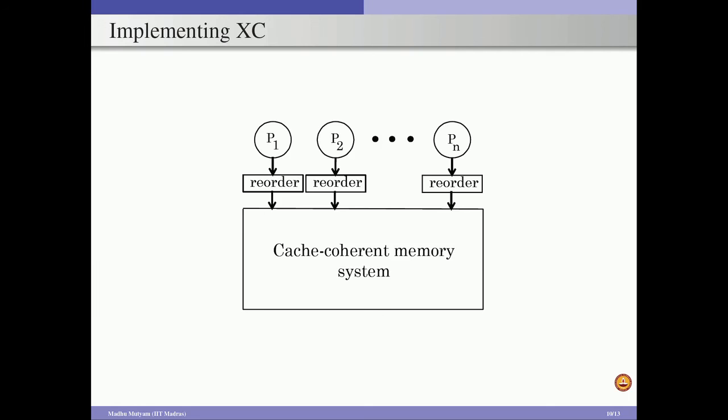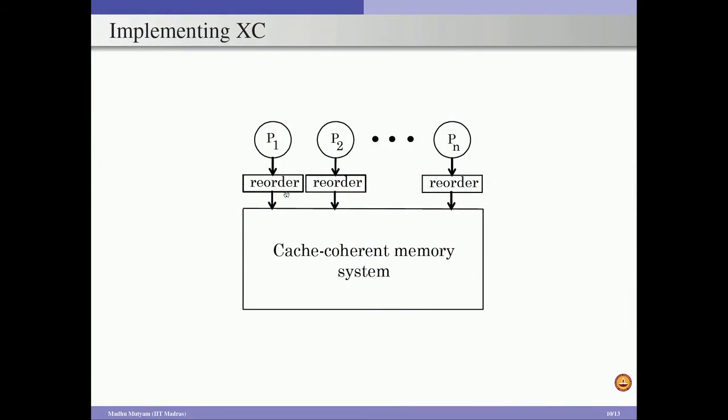And again, in order to further improve the overall performance by exploiting out of order execution using the reorder buffers, we have to relax all these memory orderings wherever there is a possibility. So that is where we come up with the relaxed consistency model. And here in the relaxed consistency model, if there is a requirement to follow the order, then we can insert a fence instruction, and otherwise we can execute instructions in out of order fashion by using this reorder buffer.